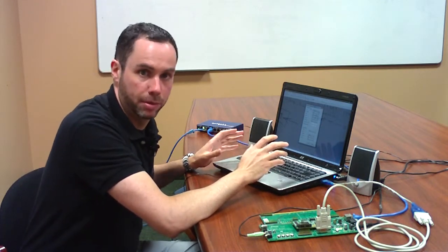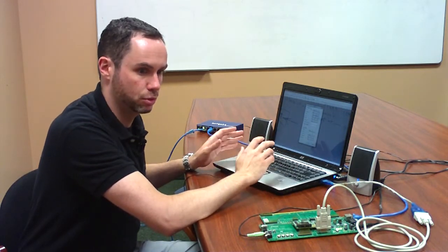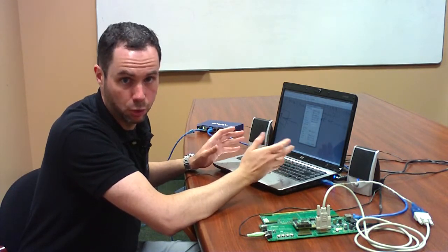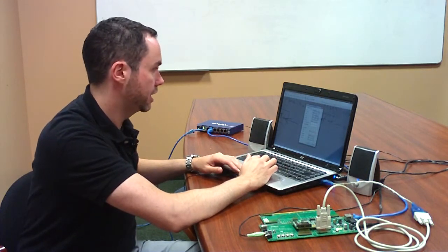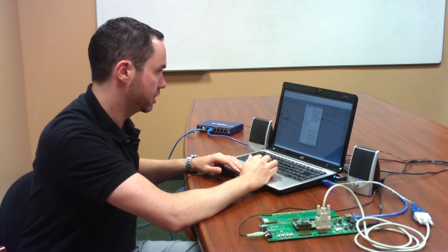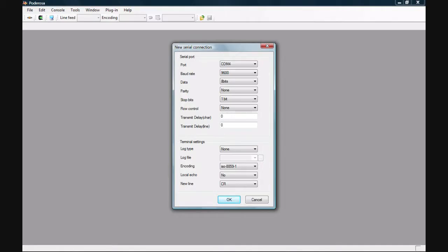Now, the important thing to remember about USB serial ports is they are dynamic. So whether it be Linux or Windows, may enumerate the port differently. So you might have to try a couple of times to find the port that your cable is on if you're using a USB to RS-232 cable. I'm pretty sure that my USB dongle is set up on COM port 4.